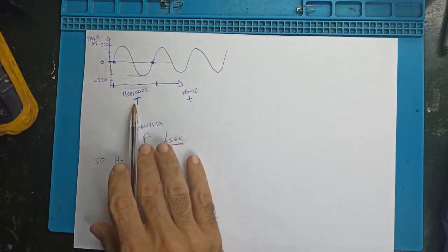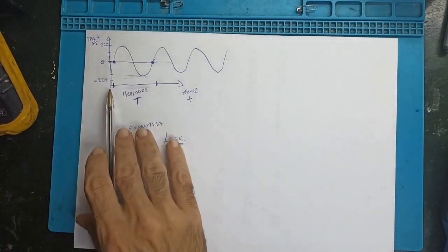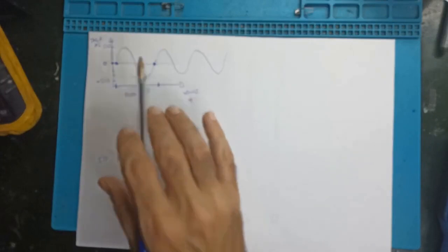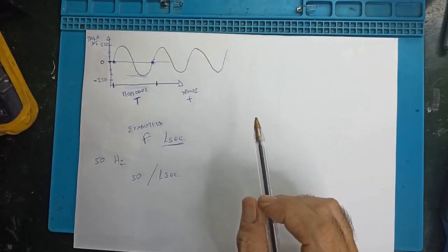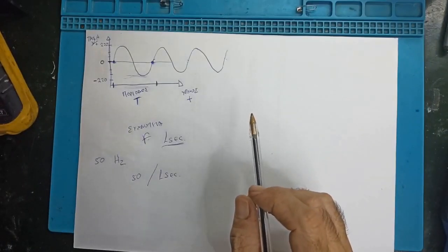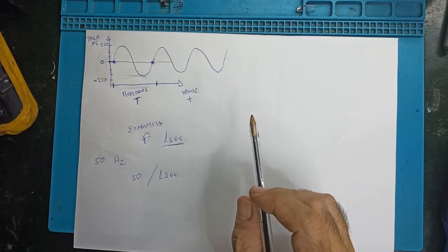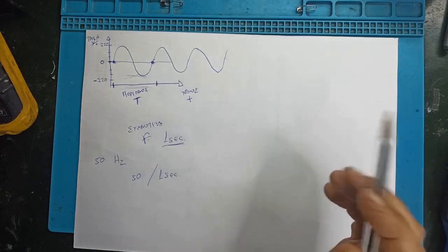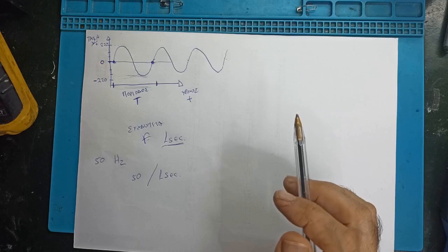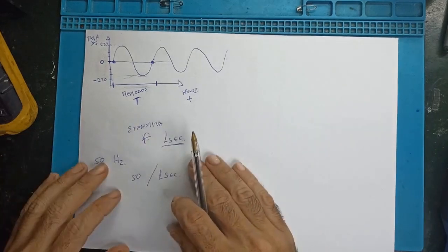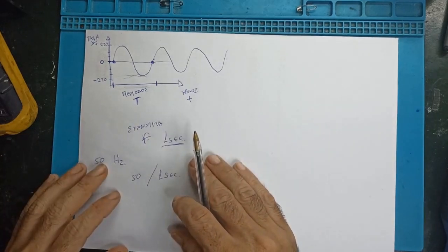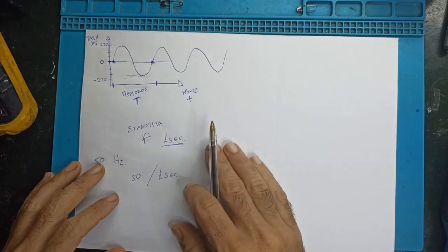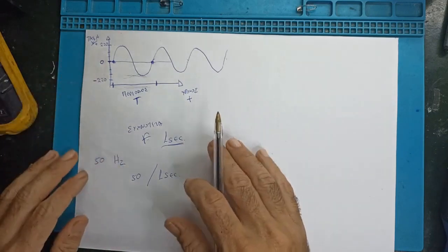They have become simpler compared to the analog oscilloscopes, where we needed to count squares and adjust. Now we simply place the probe on one of the circuit's oscillators, and immediately we see its frequency. Of course, it is enough to understand the circuit, that this is the oscillator, and that we need to measure it with the oscilloscope to see what frequency it produces.